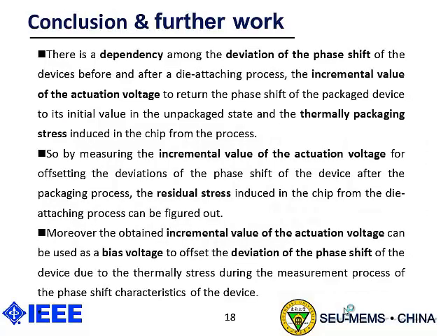Finally, the conclusion. There is a dependency among the deviation of the phase shift of the devices before and after a die attaching process, the incremental value of the actuation voltage to return the phase shift of the packaged devices to its initial value in the unpackaged state, and the thermal packaging stress induced in the chip from the process.